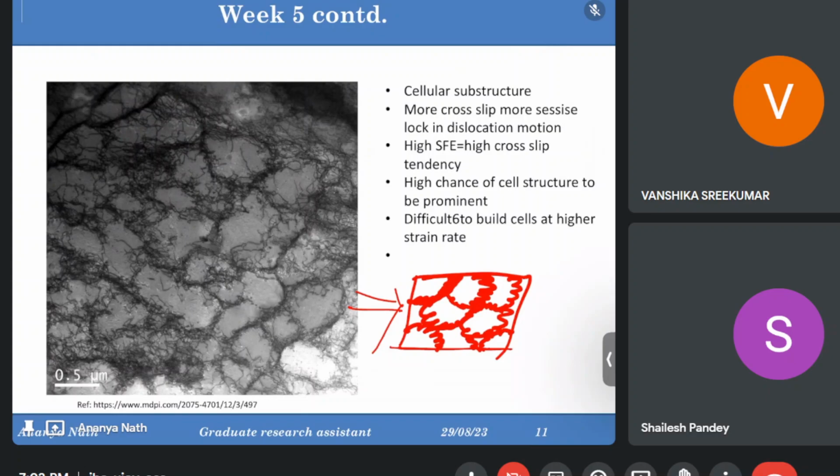If the grains are smaller, the number of grain boundaries is more, and in that case this piling up of dislocations, this type of hardening for non-heat treatable alloys, will take place easily. So generally we start with the smaller grain only, because for larger grains this will not take place that easily, since the grain boundaries are lesser in number. So this is one thing.